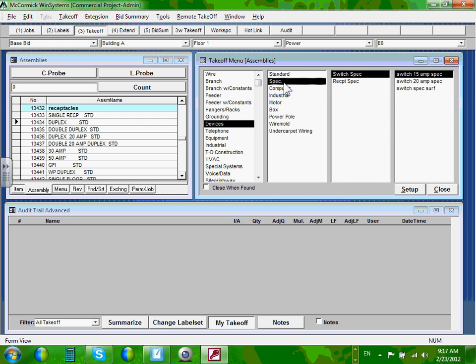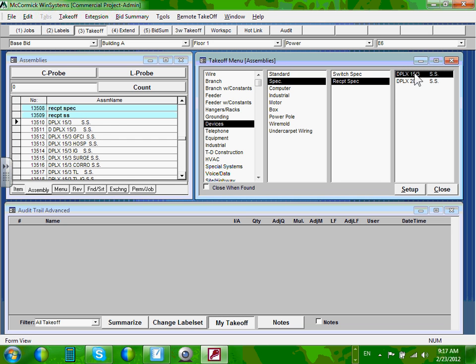No question asked. So really, most of the time is going to be on identifying the material. Now, in spec, remember the word spec with all the devices they use. Engineered projects are always spec, more expensive devices. Okay, so I need receptacles. My option is 15 amp or 20 amp. Of course, 20 amp. We don't even mention 15 when it comes to commercial building.